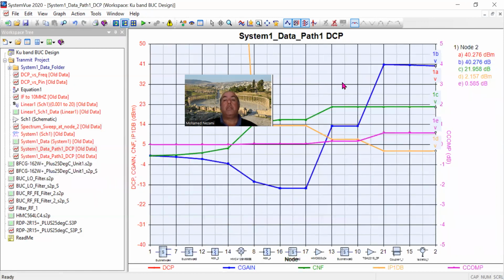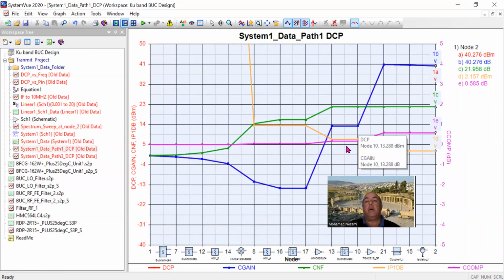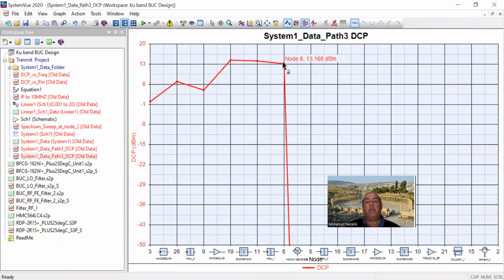So this is the progression of the gain, noise figure, compression and overall gain with the devices, starting out from the duplexer all the way to the isolator. Okay. And of course the LO port as we come in. We start out from 0 dBm and go into this side in here. This is the multiplier. It's an active multiplier, so it has an amplifier in it. Then we have the little pad, and again we amplify in here, and then we have a filter and then a pad, a little bit, until we get to the mixer in here,